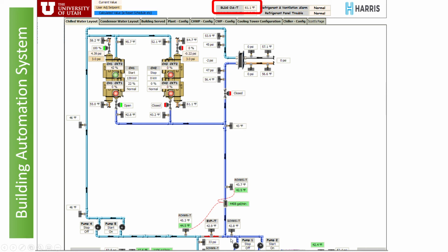The other cool thing I want to show you on here, you're like, why is there a big white space? They intend to install chillers for a future expansion of this plant. They thought they would need 2 more, but actually the plant's running efficient enough. They think they can really only just install 1 more chiller, do their expansion, and still have enough redundancy. So that's why the white space.